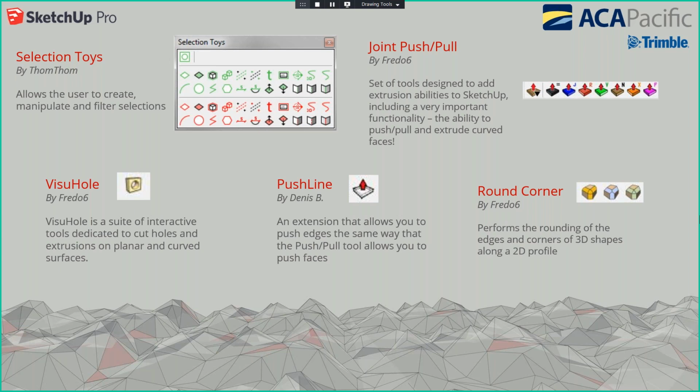The next one is known as Join Push Pull by Fredo6. This is a set of tools designed to add extrusion abilities to SketchUp, including a very important functionality: the ability to push, pull, and extrude curved surfaces. The native push-pull tool in SketchUp does not allow you to push curved surfaces, so this tool will allow you to do that and enhance a lot of your design processes. The next one is known as VisualHole, also developed by Fredo6. This is a suite of interactive tools dedicated to cutting holes and extrusions on planar and curved surfaces. Later on, I'll do this demonstration for you.